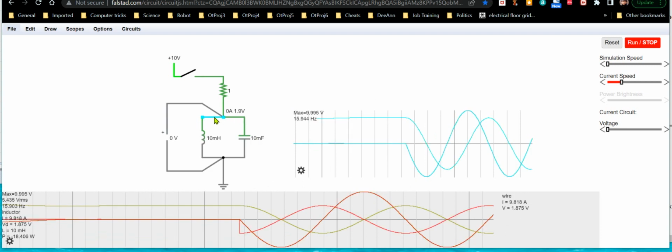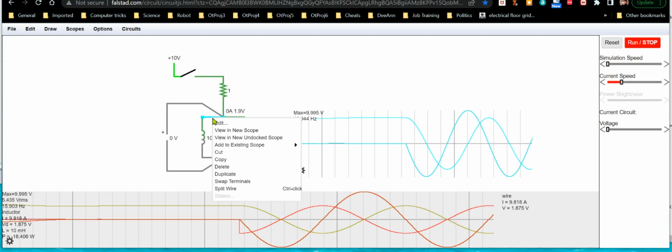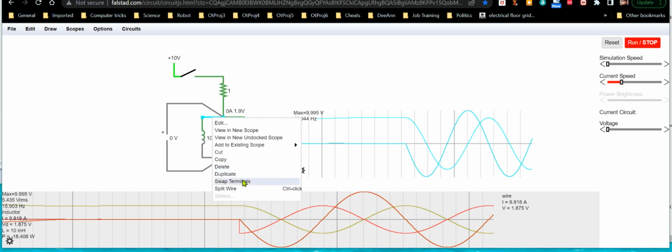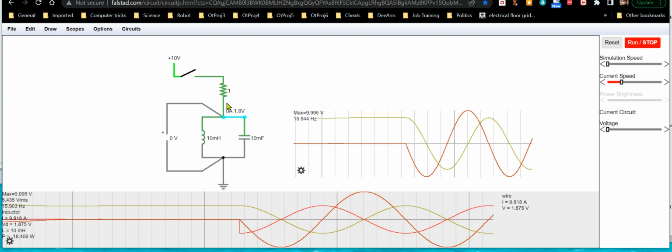Okay, but I'm measuring the current right here, and how I have this orientated, you can swap terminals anytime you want, but this is proper orientation. I got this set up so that when it's measuring current, it's positive, because here's our DC voltage source here going through a switch, and when it has current going through it, it's flowing in this direction, because the inductor, once it's basically settled into its quiescent state, which is going to be its stable state.